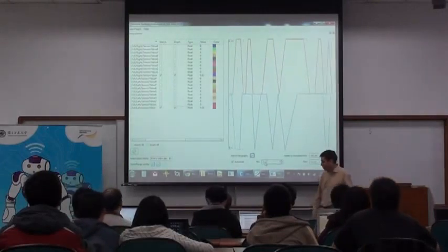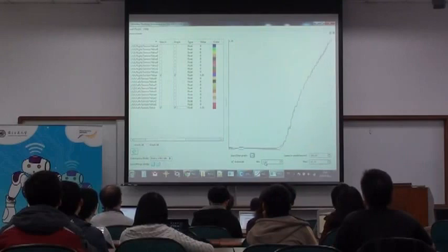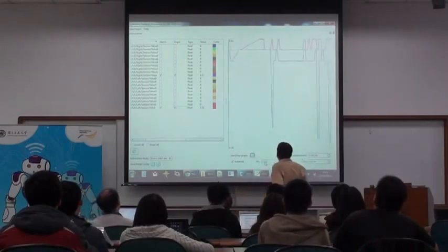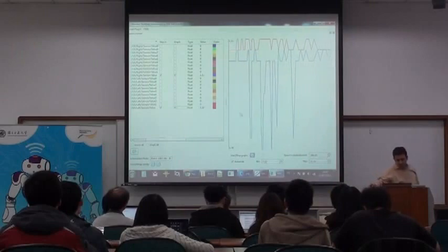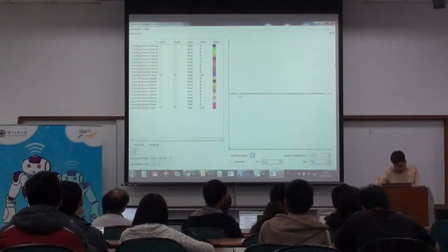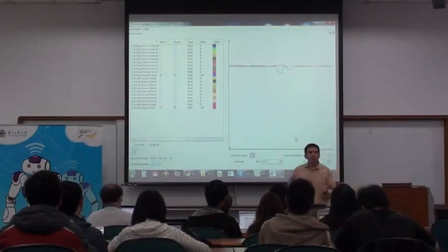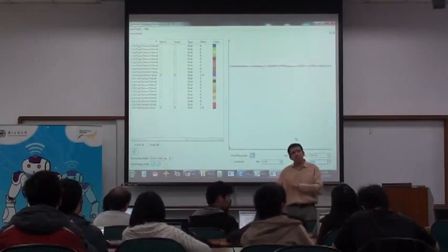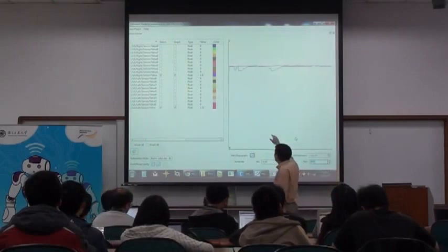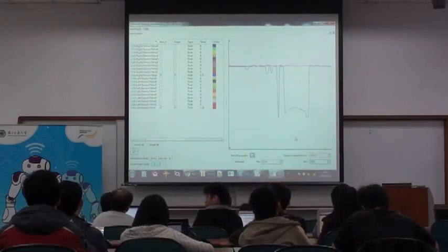So it normally gives you a distance in meters. And if I move it, okay, the distance is increasing. Well, with the auto scale it's really easy to see, so let's use a fixed scale. The sonar can measure between 25 centimeters and 2 meters maximum. So here we are around 1.5 meters. I don't have a ruler, but it's probably quite correct.